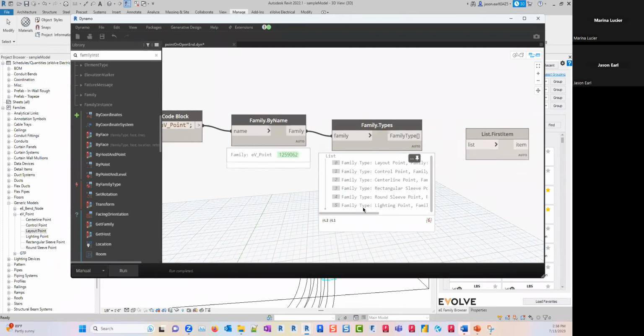So this is an example of how you can create a script to place a point in your family. Now, one thing to keep in mind, when you do work in the environment like this, when you run your script, it's essentially going to undo what you did before. So you notice I don't have a point here anymore and it placed it there. That's something that will happen. So if you're using this one, you'd have to kind of close out of it and reopen it.